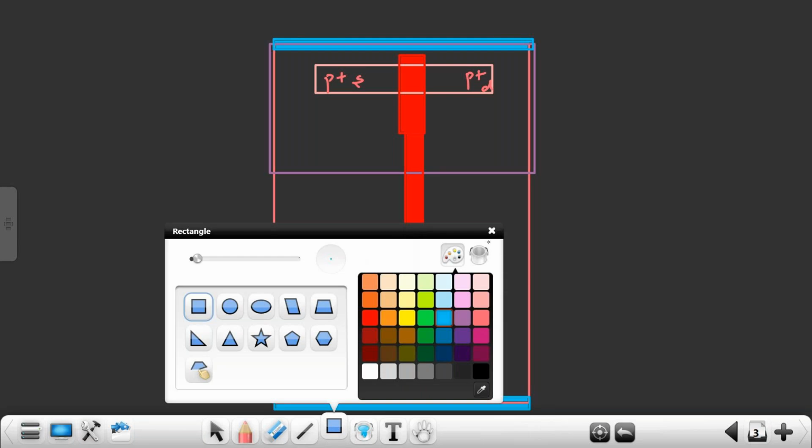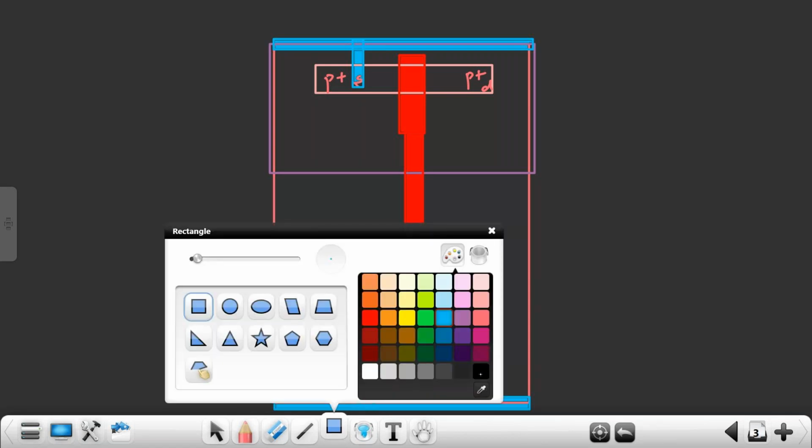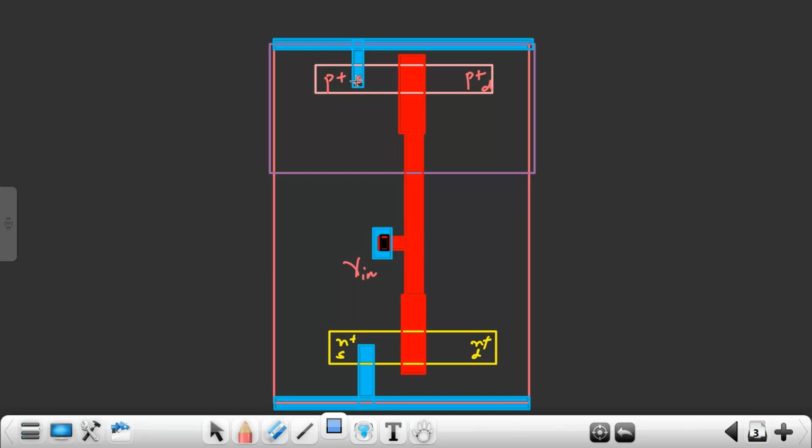And now you make a connection, right? Source of PMOS connects to VDD. Source of NMOS connects to what? VSS. So whenever, again I told you, right? This source is a P-type semiconductor. This source is what? N-type semiconductor. And blue color is what? Metal. Whenever metal and semiconductor are connecting, we should use what? Contact cut. So what is this? This is your VDD. What is this? This is your VSS.